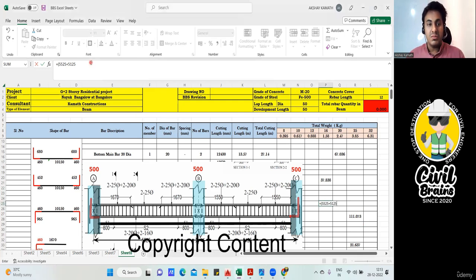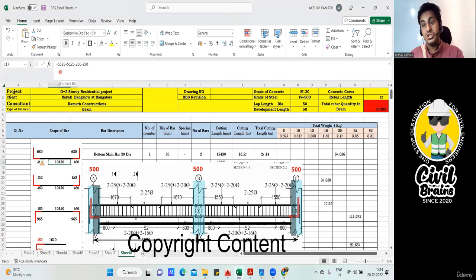I'll write minus here, minus how much? 250. Why 250? Because 500 is the overall, and from the center I want to remove only half, so it will be 250 from the left side and 250 from the right side. Agree with me? Close the bracket. Finish. This is your clear span. How much did I get? 10,150. How much did I write here? 10,150. Same thing. Understood? Very simple.